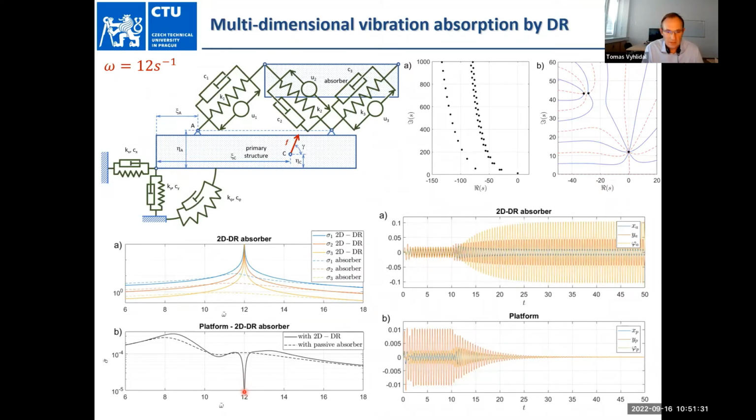Again, it is pointwise, so we can expect that it will be very fragile vibration suppression. Even small deviations between nominal and true excitation frequency will result in substantial decay of vibration suppression. But this is just the start of the research. So in time domain, you see here that it was truly achieved. After switching on the feedback, the platform is silenced, and the energy was moved to the resonator.